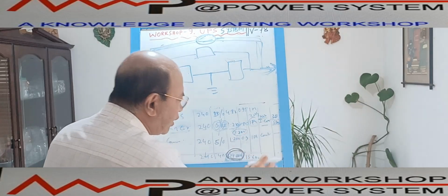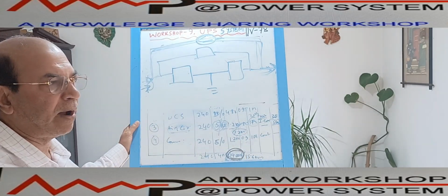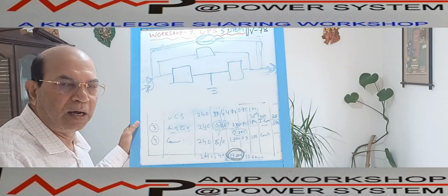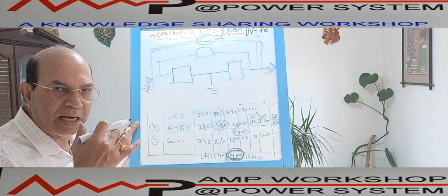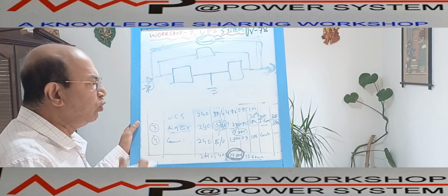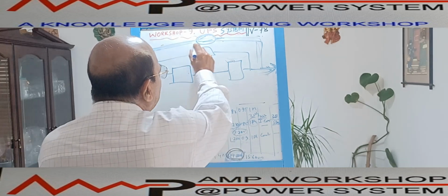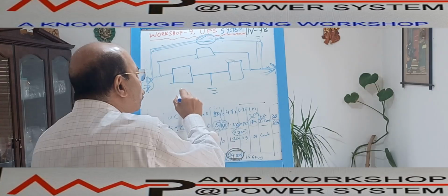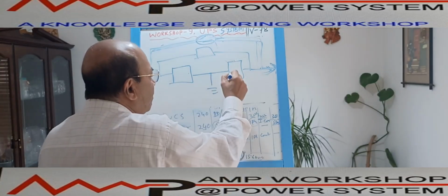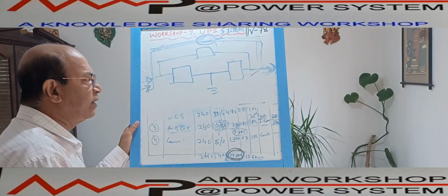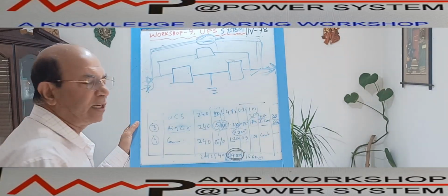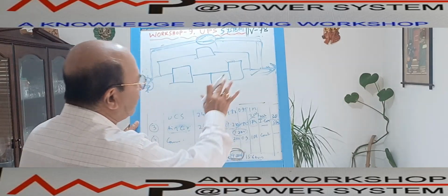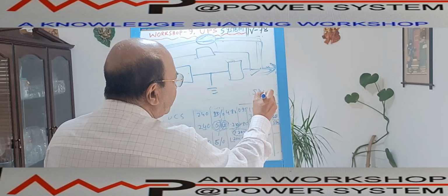Then I can switch on the maintenance bypass and it will run all these loads first. These inrush devices, suppose the circulation pump or circulation fan, generator shutdown devices, or any other startup devices required, those devices I will run through this. And once it has started, then I will switch on the UPS and transfer from the maintenance bypass to the UPS. In that case, the UPS will not be subjected to the inrush current. So that way, the UPS system sizing will remain 15 kVA.